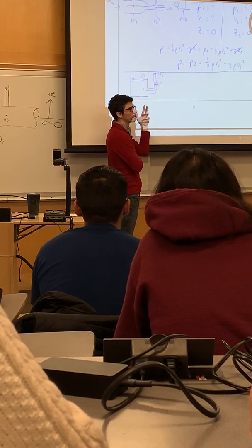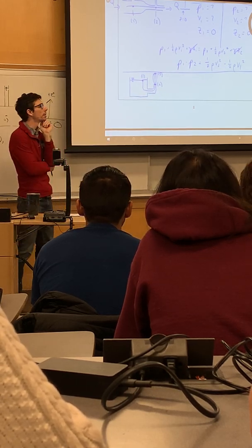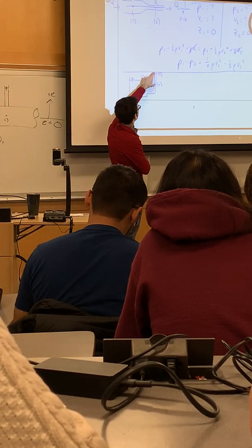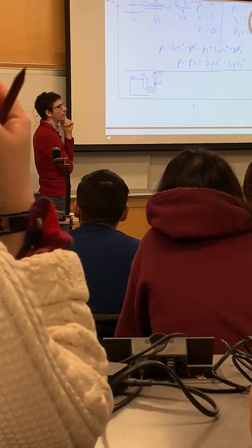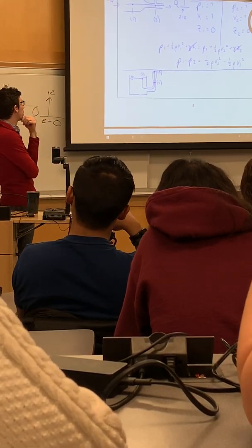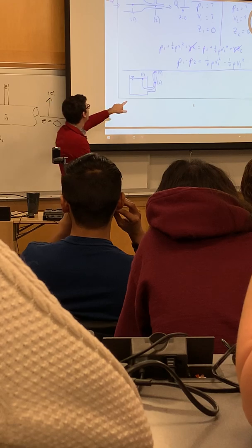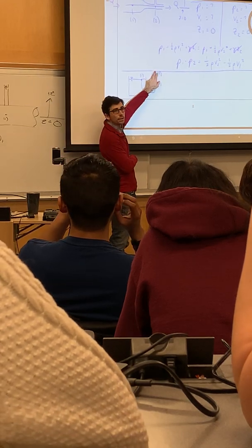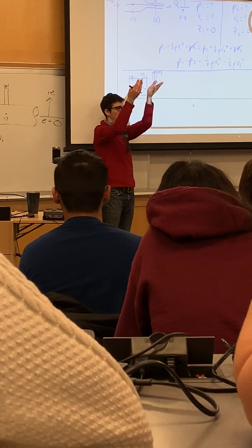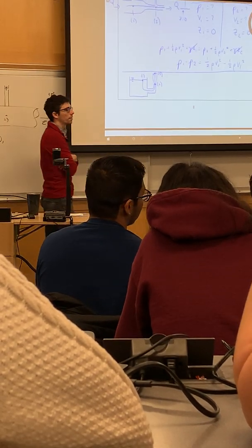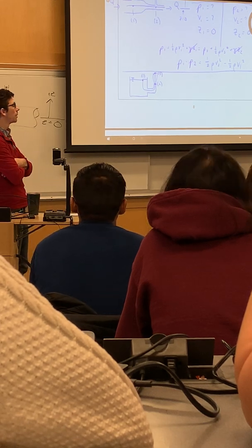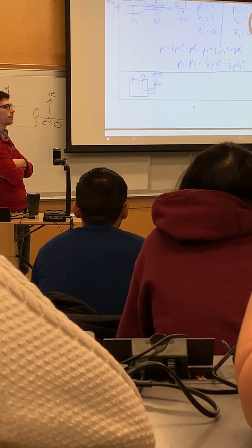Z3 minus Z2. You have to know something about that to solve for. Well, that's probably what you'd be solving for. What's the velocity at point 3? 0. Right? That's sort of the trick in this question, is acknowledging that the peak extent of this free flow is going to expend its velocity in exchange for height. So we can apply Bernoulli and get an approximation of what the height of that jet would be.